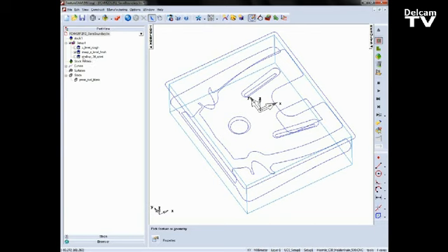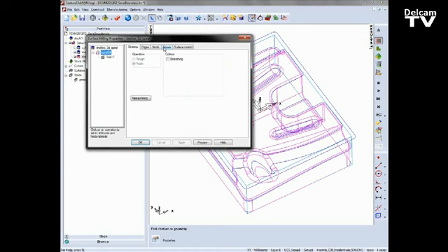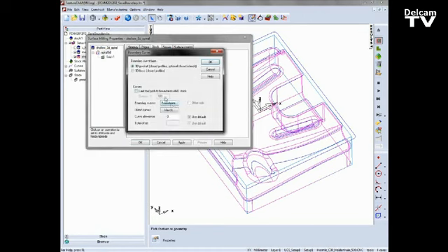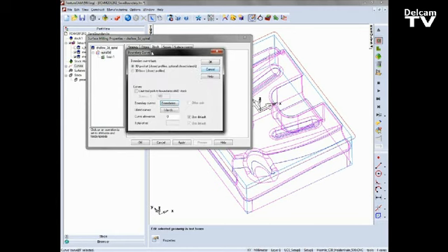So let's go to the shallow 3D spiral. I'm going to go into the properties of this, into the stock tab. I'm going to say select curves for boundaries, and then for the boundaries I'm going to select all of the curves. So all of those are selected. The only one I don't want to use is this one here, which in the case of my model is the top one, curve 19. So I'm now restricting that toolpath to only work within the boundaries from these shallow regions.